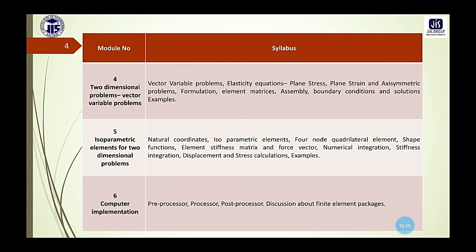Lastly, we have the post-processing part in the software simulation. In this last phase, we check the validity of the generated solution. We must check the validity of our result. Next, the values of primary quantities, such as displacement and stresses, should be examined properly, to see whether our result is up to the mark and almost accurate or not, and if it is not accurate, what the error percentage is. All these things will be discussed in the post-processor part.